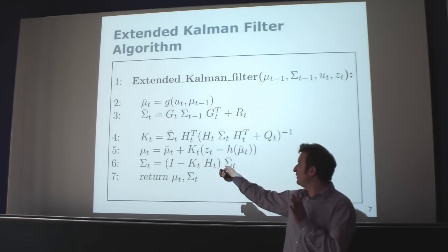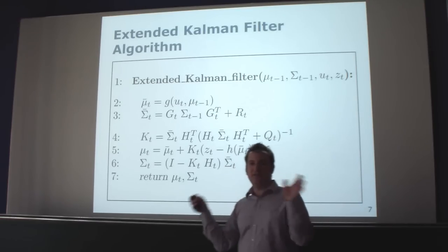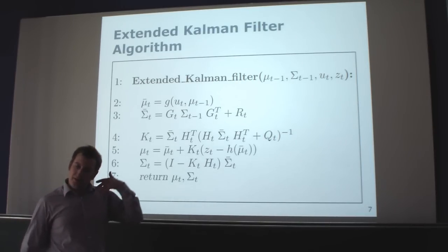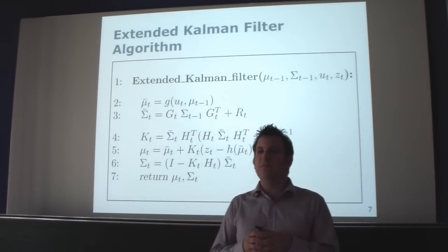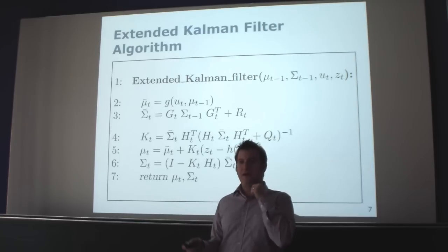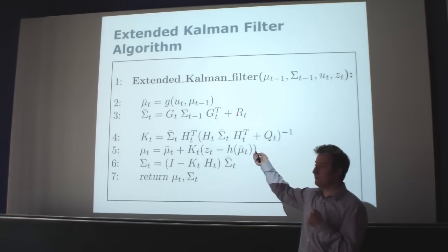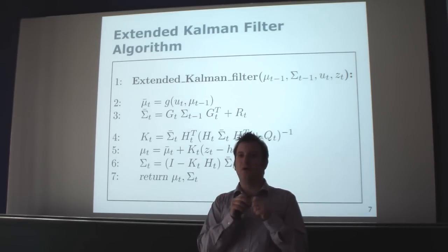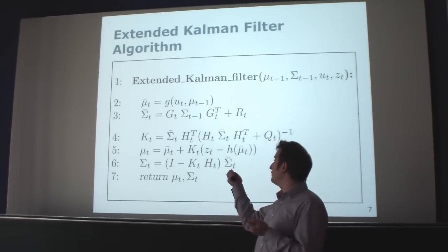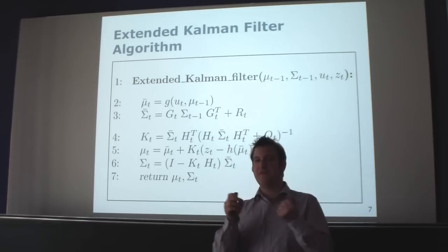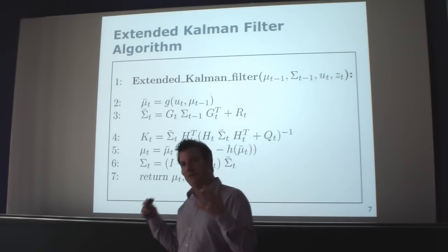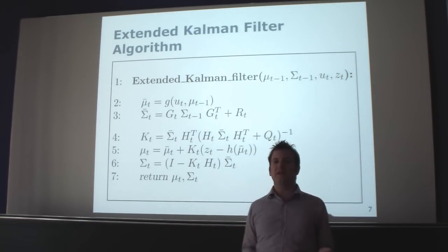If you, for the moment, ignore the nonlinearities and assume that these guys here are identity matrices, so we have a linear function, and there's no scaling or things like that involved, then simply adding the term R_t increases the uncertainty of the system based on the motion uncertainty. So if I'm very, very certain how I move, the values in this matrix are typically very, very small. So there's a small uncertainty, and then the increase of the overall uncertainty is also small, because it's just an additive term. These matrices are added up. If I have a high uncertainty in my motion, the elements in this matrix, especially the diagonal elements, are typically very large, and this leads to a significant increase in uncertainty.